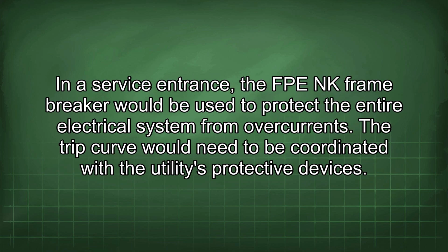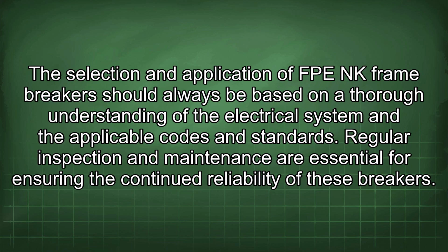In a service entrance, the FPE NK frame breaker would be used to protect the entire electrical system from overcurrent. The trip curve would need to be coordinated with the utility's protective devices. The selection and application of FPE NK frame breakers should always be based on a thorough understanding of the electrical system and the applicable codes and standards. Regular inspection and maintenance are essential for ensuring the continued reliability of these breakers.